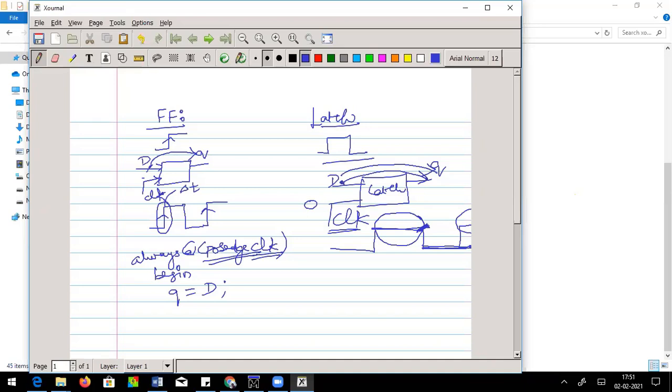So the main difference is the latch opening window period is large compared to that of flip-flop. Remember, all synchronization takes place only with flip-flops. The reason is that only then can all those data be synced at the proper rise edge or fall edge. You can go with rise edge or fall edge, that's left to you.